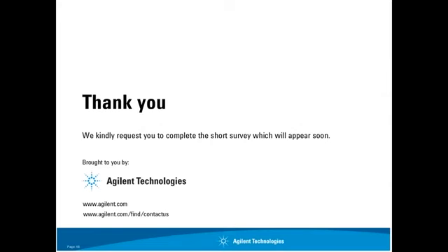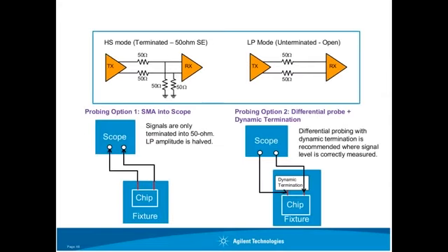Yes, thank you, Jürgen. Minji, for the first question, would you mind going to slide 17? It deals with that slide. So the question is, does the 50 ohm series resistor represent the output impedance of the driver or the characteristic line impedance? That's the output of the driver and the characteristics of the channel as well. So there's a need to maintain that 50 ohm from the output of the driver across the trace. That's the 50 ohm environment that has to be maintained on the D-PHY line.